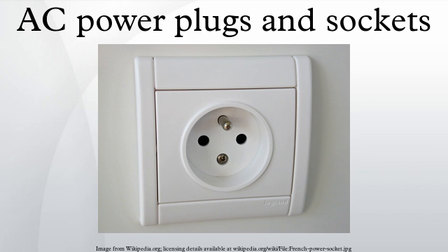It helped domestic consumers that most of the Class II plugs fitted in the new NBR 14136 sockets. However, very few private houses have an earthed supply, and even if a 3-pin socket is present, it is not safe to assume that all 3 terminals are actually connected without testing. Most large domestic appliances are sold with the option to fit a flying earth tail to be locally earthed, although many consumers are unsure how to use this and so it is not fitted, effectively using the equipment as Class 0.